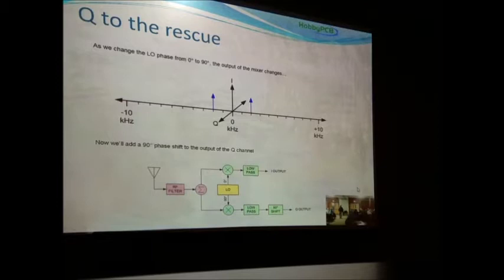Well, in a wideband digital receiver, wouldn't your original sampling be done before you're mixing? Well, right. In a direct sampled one, it certainly would be, but not in an IQ.